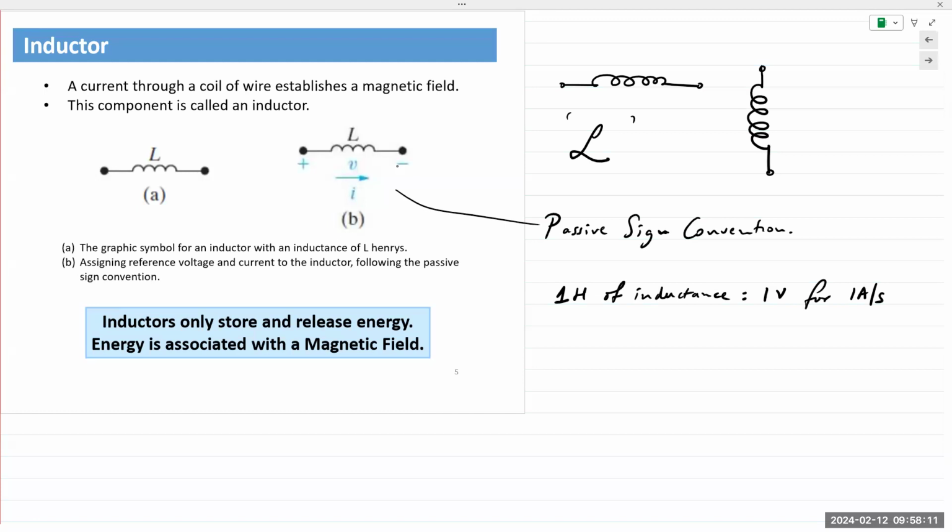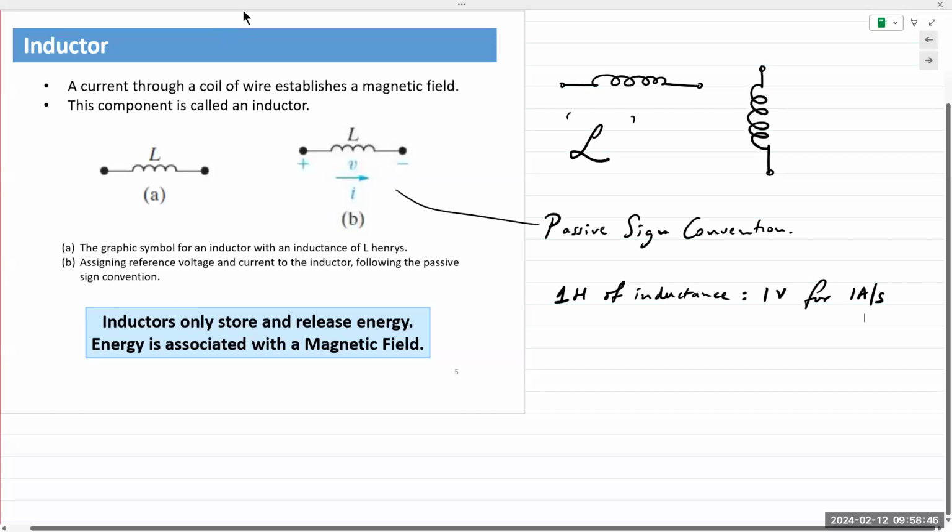Again, if we take this much further, we get into the physics, and so I always want to avoid doing that. But it's just important as a concept for students to know what an inductance is. If current is constant, the voltage across the inductor would be equal to 0. The current has to change. When it changes, it establishes a voltage across it. That voltage level, if it's 1 volt for every 1 ampere per second change in the current, then we say it's 1 Henry. Typical inductors that we use in electrical circuits are very, very small.